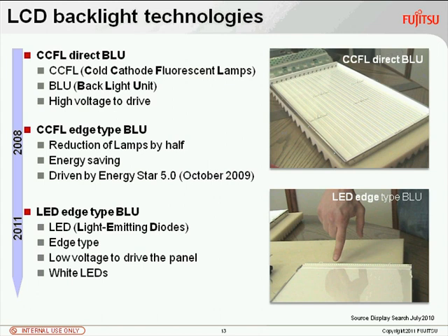They reduced the number of lamps to half, so they used 4 or 2 lamps in future, and they put the lamps on the side, on the left and on the right side. And to spread the light, they used a light guide, which is a glass plate, mirrored on the rear side, and distributes the light over the whole screen.